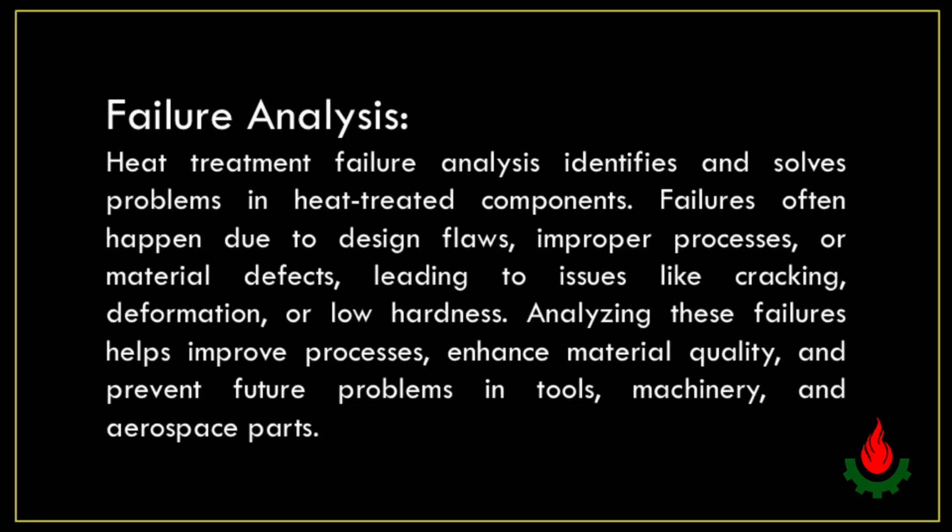Failure analysis. Heat treatment failure analysis identifies and solves problems in heat-treated components. Failures often happen due to design flaws, improper processes, or material defects, leading to issues like cracking, deformation, or low hardness. Analyzing these failures helps improve processes, enhance material quality, and prevent future problems in tools, machinery, and aerospace parts.